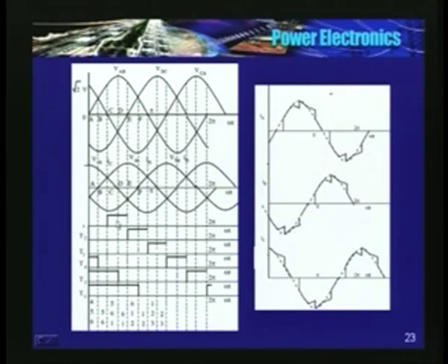Okay. See, I will show you the phase voltages. After 30 degrees, somewhere at this point, see, VCN is becoming 0. So T5 turns off. So I have stopped, or this is the boundary for T5 gate pulses.